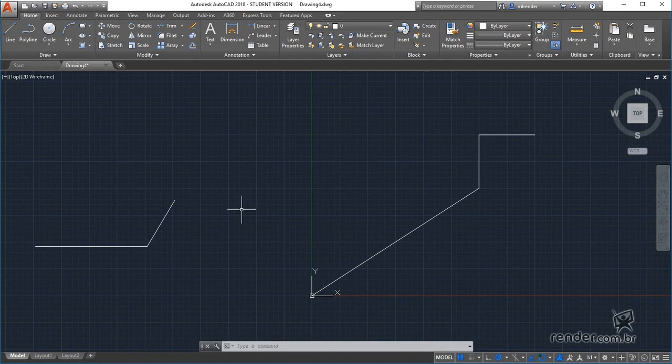In addition to using these coordinate systems, we can enter absolute or incremental coordinates. Absolute coordinates use as a basis to define distances from the point of origin of the program. Whenever this type of coordinate is used, we must insert the pound symbol at the beginning of the coordinate.